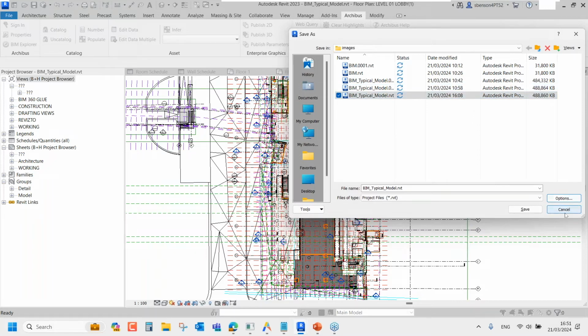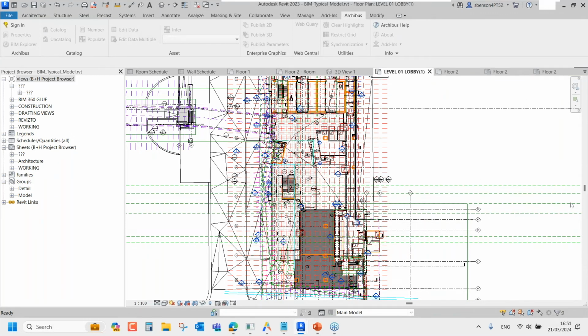So step one is get this to be a separate set of files from your initial BIM models. Step two is remove any inactive links. For example, you're going to find that there's a lot of links in Revit that were used to connect different models and different drawings. Some of them you may choose to keep and retain. Other ones you may need to get rid of.